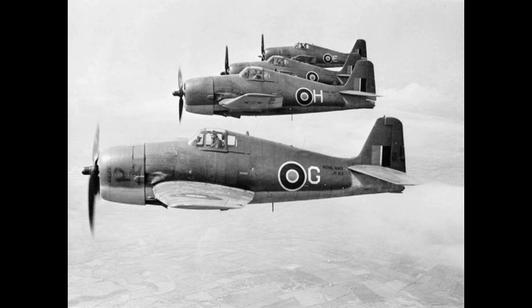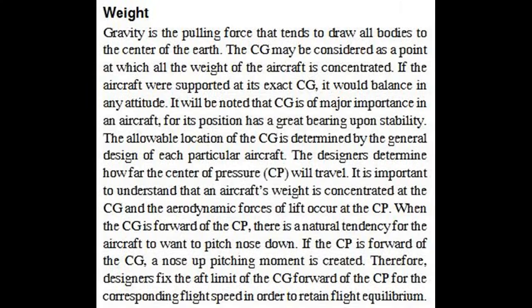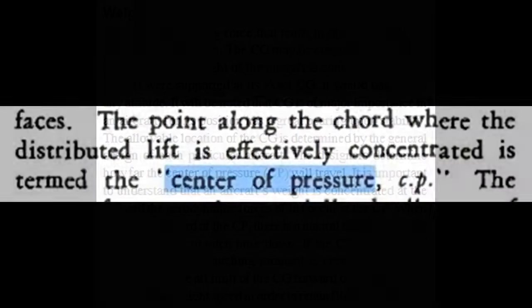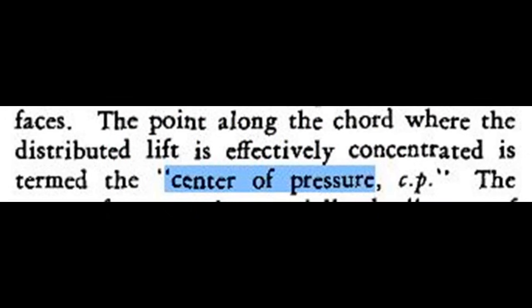The wing is, of course, providing us lift. The actual amount of lift varies across the entire surface of the wing, but in the same way that center of gravity works for weight, the center of pressure works for lift. Thus, lift can be thought of effectively as acting through one point, which we'll call center of pressure. Feel free to pause here if you want to read the official descriptions of these terms. Here are both from the Pilot's Handbook of Aeronautical Knowledge and the Center of Pressure from Aerodynamics for Naval Aviators, the two books I'll be using.